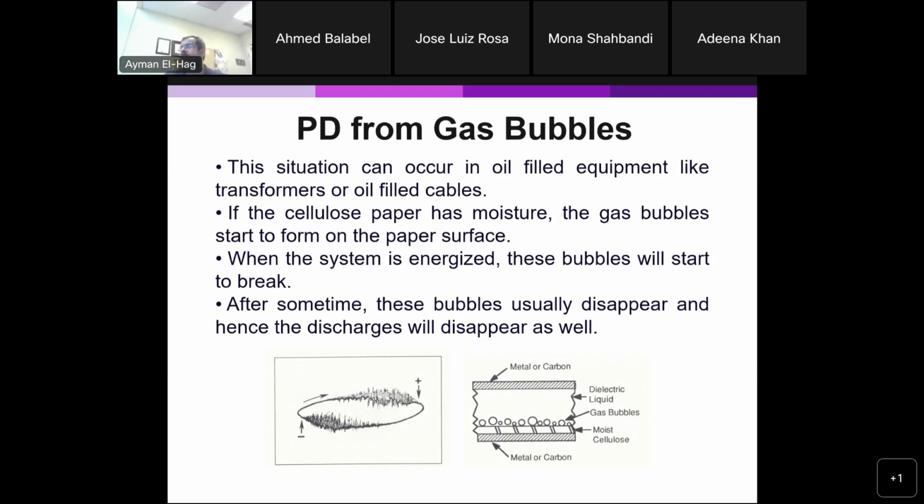I remember a story in Canada, without mentioning names, one of the big well-known manufacturers was making phase shift transformers. Those phase shift transformers, we use them to block the power. So if you want to control the real power flow, you control the angle between one point and another. The real power goes from the voltage with a higher angle to the voltage with a lower angle. So if you can change the phase shift, you can block the power.